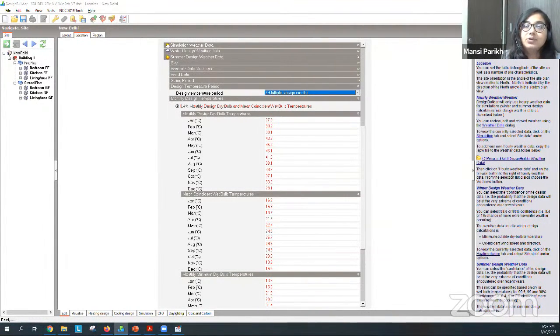I would give you a simple example. It is very much conditional where you actually provide your insulation. If in a cold climate you want to retain the heat gained from the glazing, then you have to provide the insulation on the inner side probably. In a hotter climate, you want to stop the heat coming inside right at the beginning, so then you provide your insulation probably on the outer side. So it is very much dependent on the weather and every other detail like conditioning and other things.